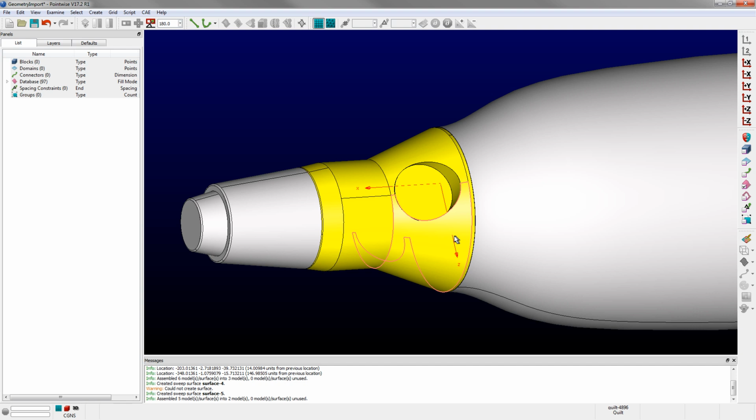So a quilt is going to consist of a number of underlying trim surfaces. Now the underlying geometry for this section is actually a cone, okay, that has been trimmed with a cylinder, and all of that information is actually in the background, and we really want to recover that conical surface, and the way to go about doing that is to untrim this quilt. Okay, again, a lot of that information is in the background.